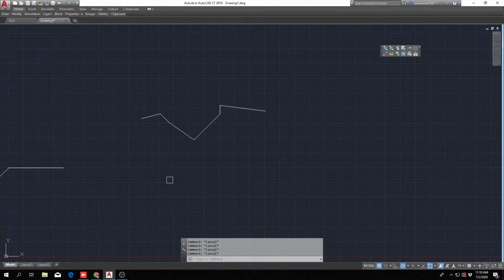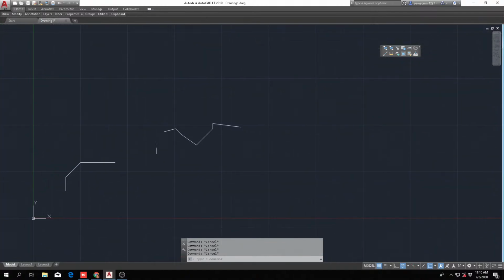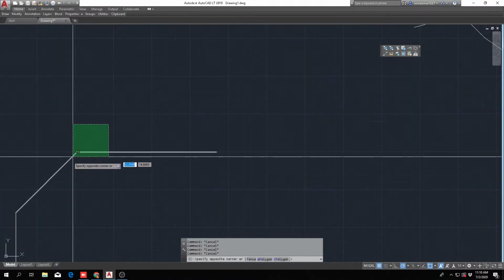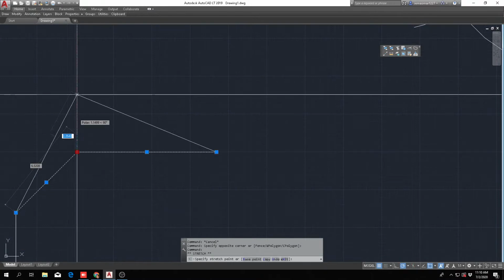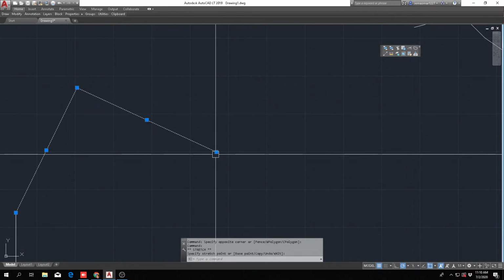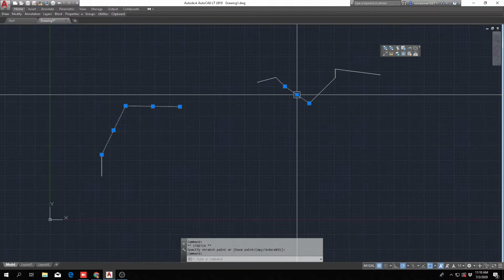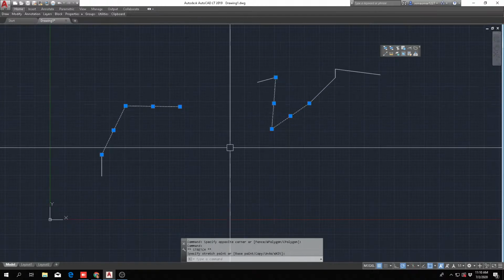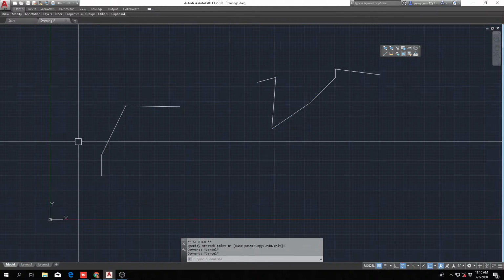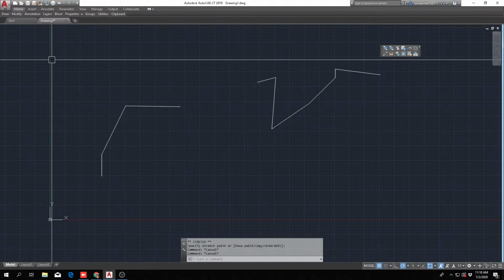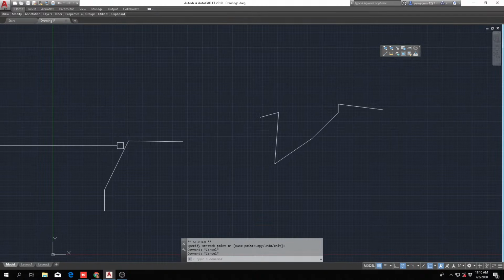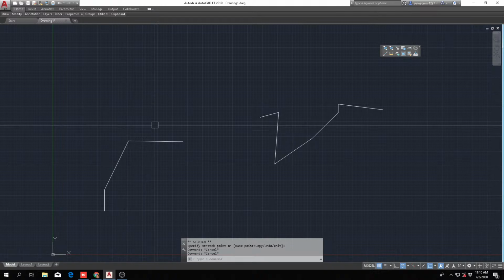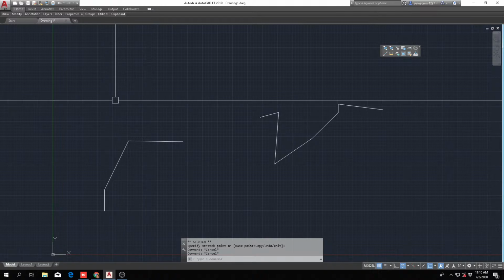Now you might say, hey, I already know how to stretch, because last time all you did was highlight the lines, get it from a point, and just stretch it, right? So you get it from a point, you stretch it. Yes, that's a way of stretching it, but there's also a command called stretch, and it is useful because you can stretch two lines together that are apart.